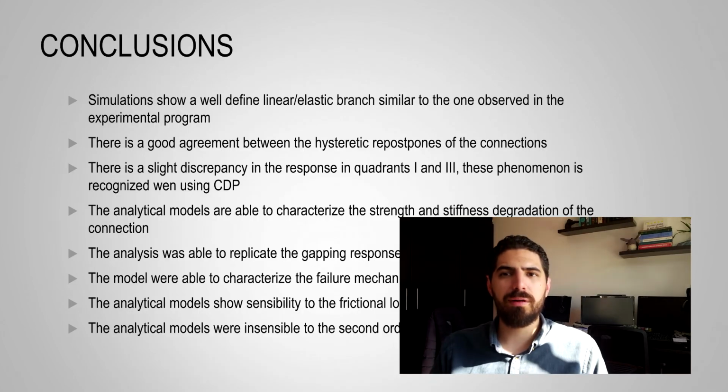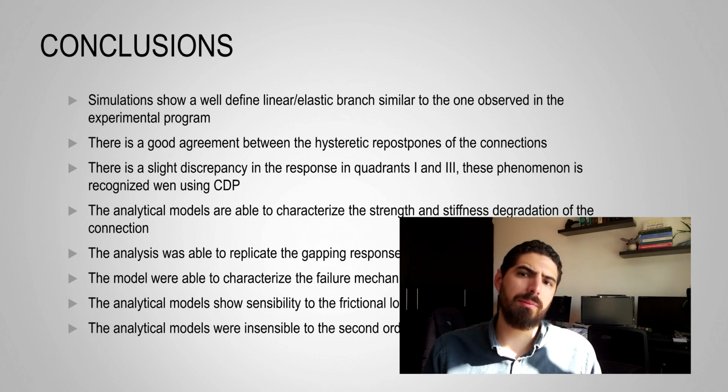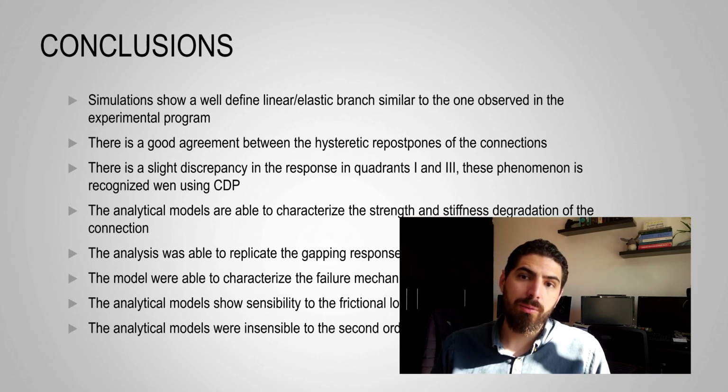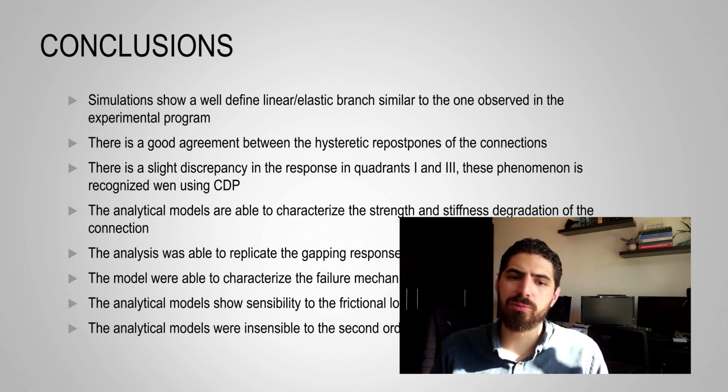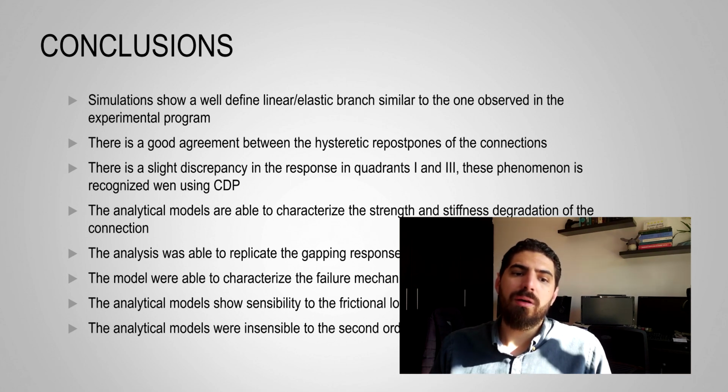We can see that the overall trend in the connection response is really well characterized. We have a linear elastic branch that exhibits a similar trend to the experimental program. Also, the overall hysteretic behavior is well matched. Additionally, we were able to characterize the strength and stiffness degradation in the connection. And finally, we were able to replicate the gapping response and the failure mechanism in the connection.